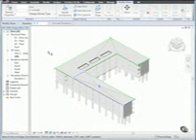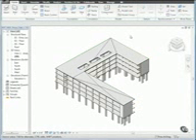When you do, the roof slab will then display with edges representing the sloping faces leading down to the roof drain. You can use the same method to modify the remainder of the roof to accommodate the drainage conditions. Press Escape twice and let's create a section.